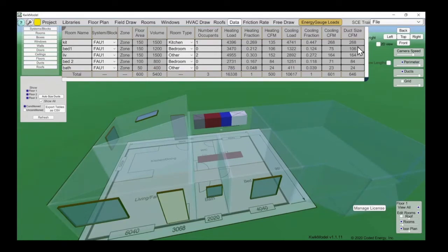Now, I'll just kind of forewarn you and say that may or may not change the duct sizes. When you start sizing ducts, as we'll see in a second, you're going to round up to the next duct size, and sometimes that gives you a lot of extra capacity, and sometimes it's enough to handle the difference between the heating and cooling airflows, okay? So that'll make more sense when we get to that point, okay? So these are the actual CFMs we're going to size each duct to in each room, okay? But before we do that, we have to do something called a friction rate.